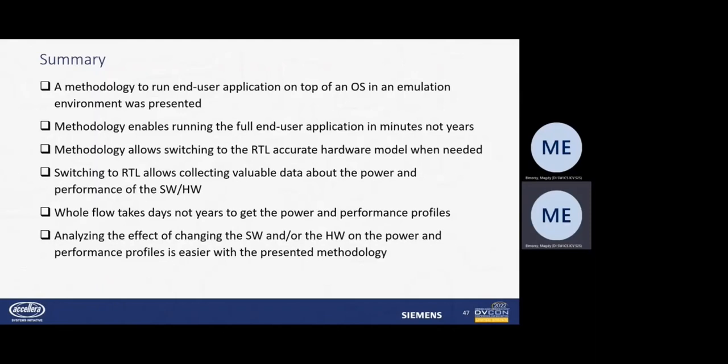The methodology is using sampling in order to get the power profile in hours and days rather than years, for such an end user application running on an operating system on the RTL. We use the Veloce hardware accelerator as our emulation engine.